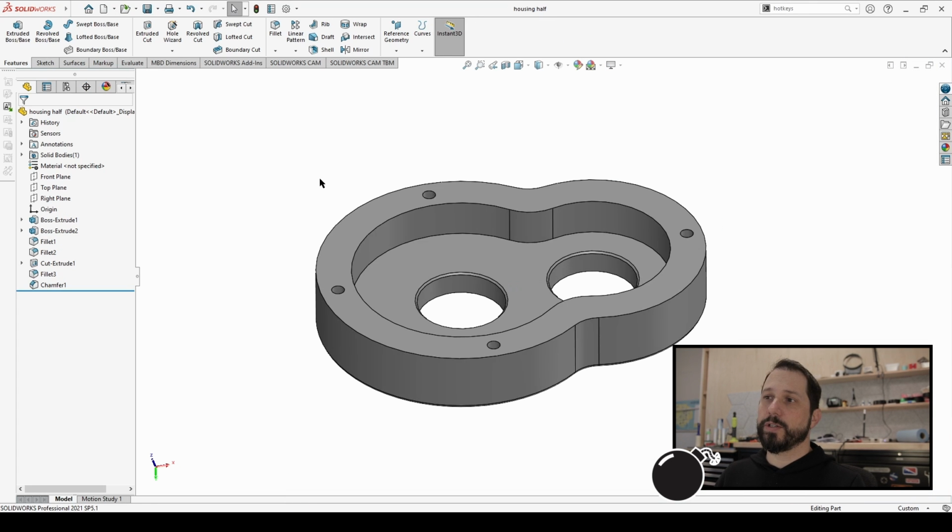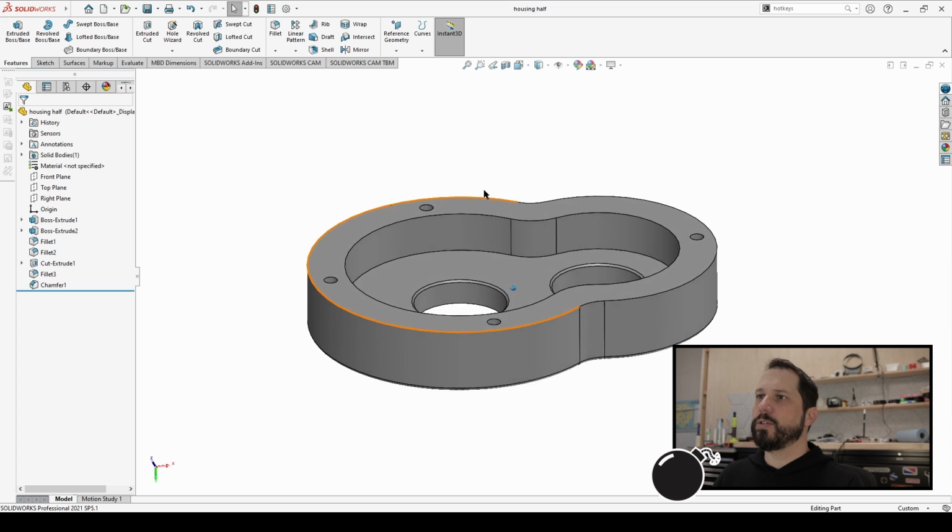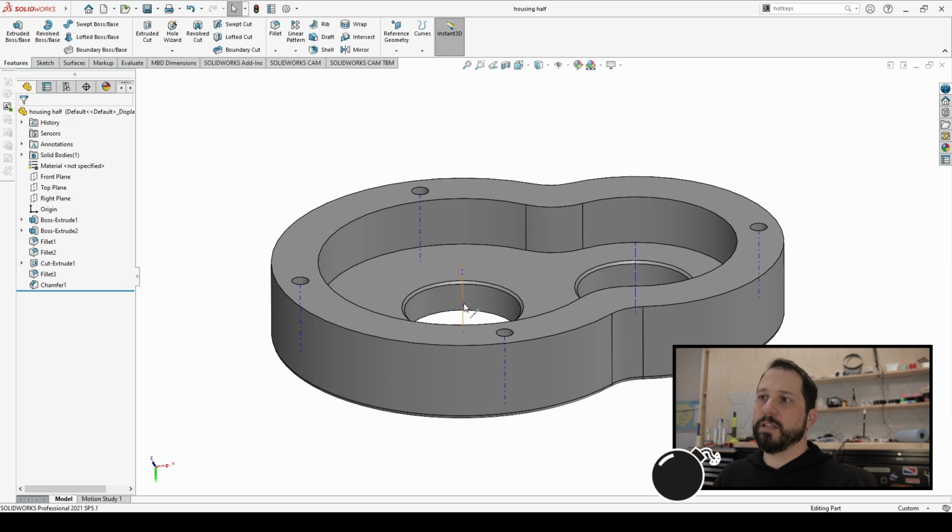Sometimes in a part or an assembly, if you want to do a sketch or a mate, and you want to align something with the center of this bore, but for some reason you can't pick whatever surfaces you would normally pick, you can also turn on temporary axes. So this is regular axes, so you'd have to go in and actually create an axis where you wanted it. If you click View Temporary Axes, then it puts a temporary axis on anything that's cylindrical.